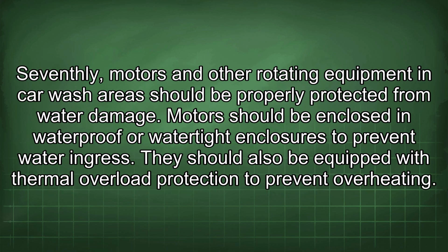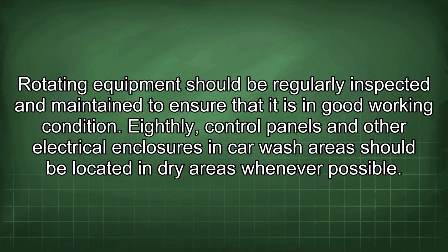Seventhly, motors and other rotating equipment in car wash areas should be properly protected from water damage. Motors should be enclosed in waterproof or watertight enclosures to prevent water ingress. They should also be equipped with thermal overload protection to prevent overheating. Rotating equipment should be regularly inspected and maintained to ensure that it is in good working condition.